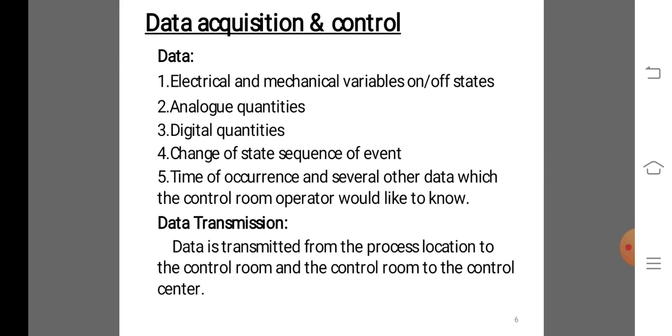Supervisory control indicates that the operator residing in the energy control center, ECC, has the ability to control remote equipment. Data acquisition indicates that information is gathered on the status of the remote equipment and sent to the ECC for monitoring purposes. The monitoring equipment is normally located in the substation and is consolidated in what is known as the remote terminal unit, RTU.